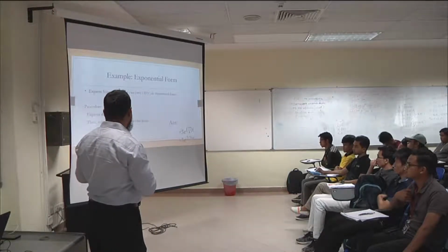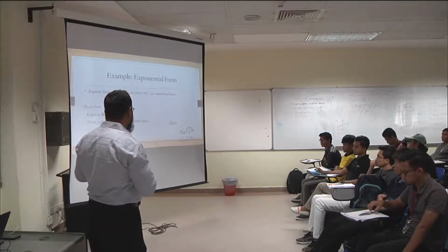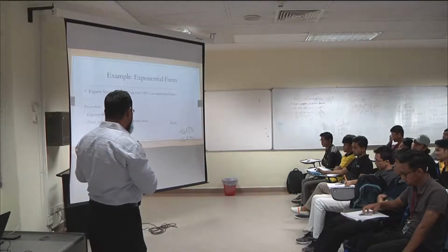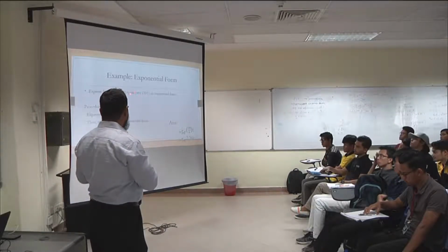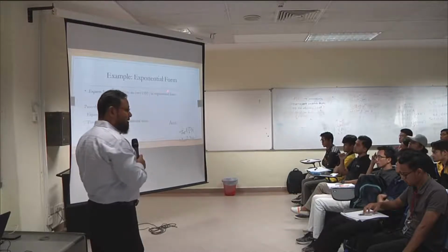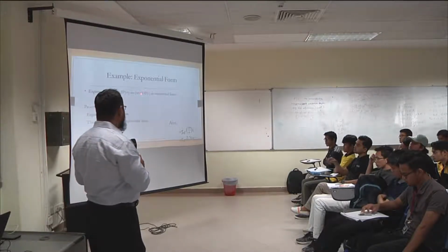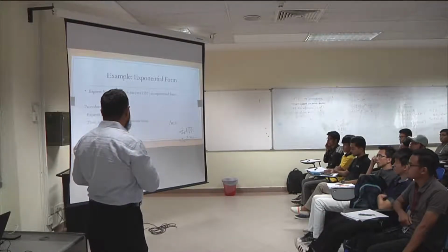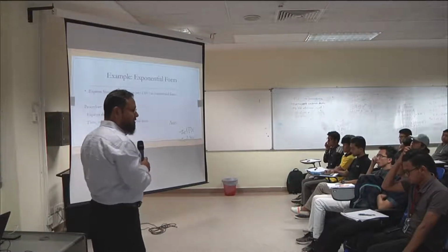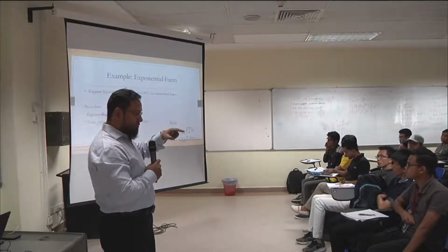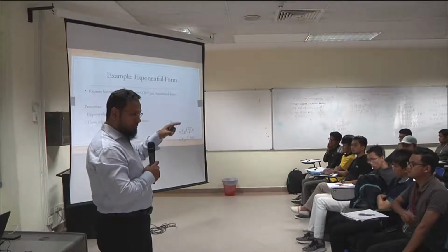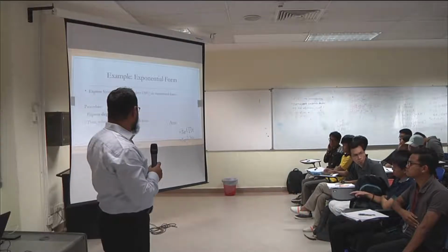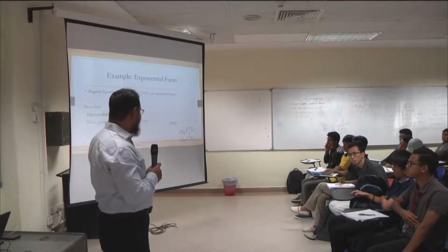So using Euler identity, we can represent this in an exponential form. So in an exponential form, it would be, again, e to the power plus minus j of omega t plus 135 degrees. Remember, you cannot use degrees. You have to use radians in Euler identity. The angle in the power of the exponential, you must use radians, not degrees. And this would be the answer.